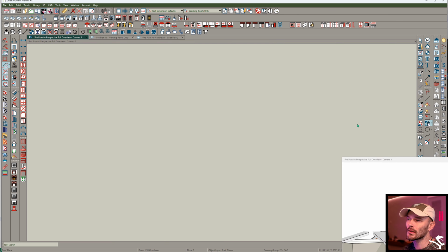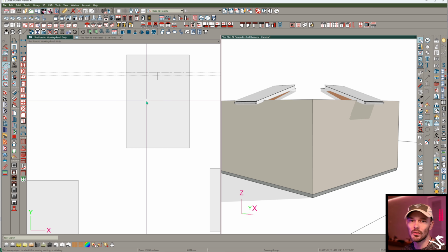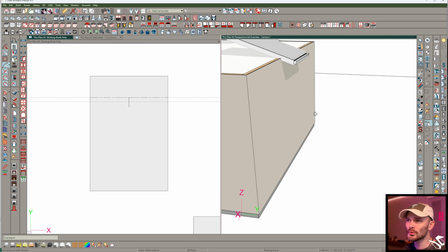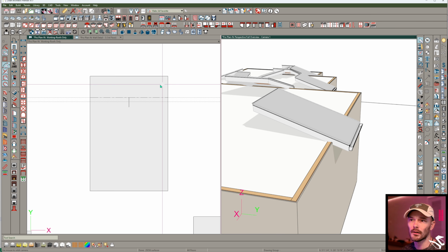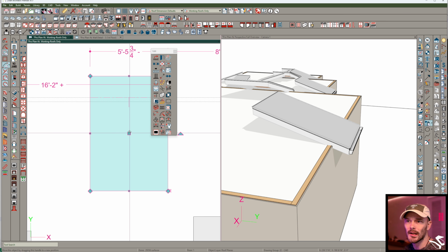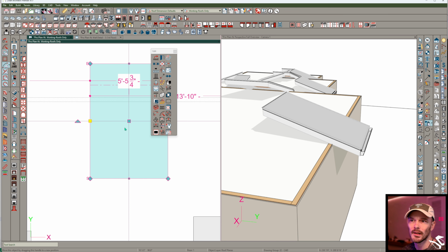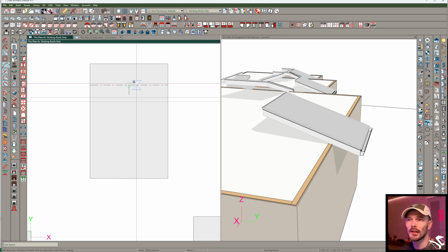Let's get back to this little 3D view here, and I'm going to show you what happens when we make some common little mistakes. Okay, I'm trying to conform a roof. I'm trying to figure out how these roof tools work. And so what I'm doing is, hey, I know that the overhang here is incorrect. This is 1'6". It needs to be like, I don't know, 2'4". So I'm just dragging the center edit handle of this roof plane. That's a mistake. Why? Because it moved the baseline. So the correlation between the baseline and the main wall layer of our wall assembly just changed.